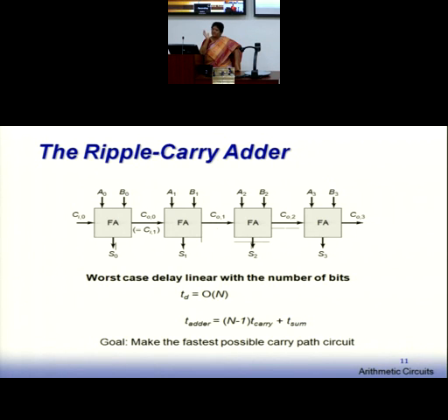First bit generate and rest all propagate. So this is our worst case delay combination, and our delay is governed by this condition. Okay. So you can express the total adder delay now. If I represent my total adder delay and there are n bits, so first of all compute all n-1 carries, and finally compute the last sum bit.